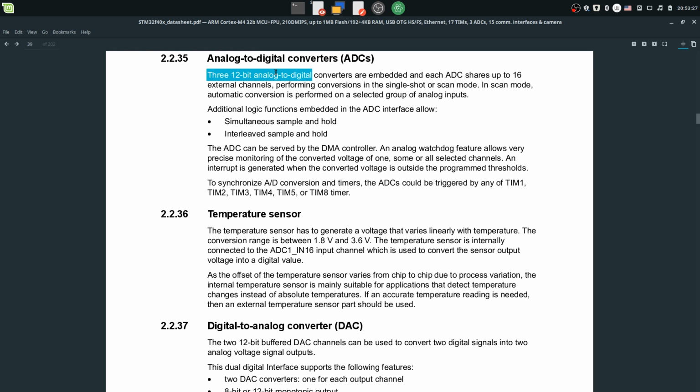In Arduino we only used analog read and that did everything automatically, but now we have to do this from scratch. So if you read from more than one pin, we have to use some kind of memory copying from our data register, from our ADC, so the new value from another pin can arrive into that register before it gets overwritten. That's why we will use the DMA to do that for us.